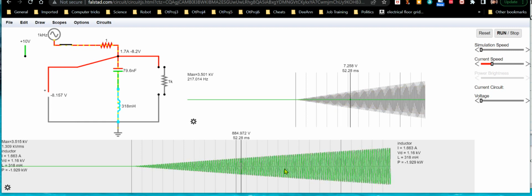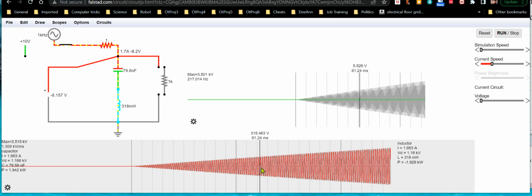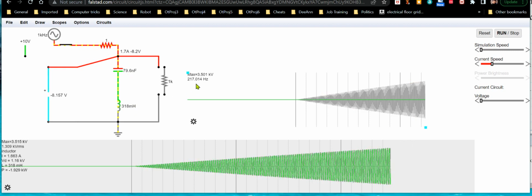I need to make some adjustments here in a few minutes so that you can actually see the frequencies and everything that's going on, because this is set to 1 kilohertz right here, and I've adjusted the values to where this is all in resonance. Because if I remember correctly, that's where this effect maximizes for both components, at resonance, because they're going to be equal and opposite voltages for the current involved.